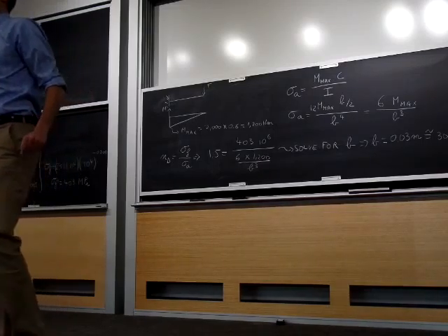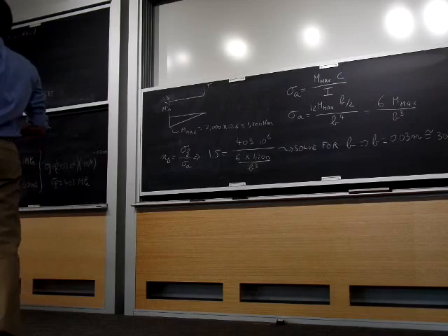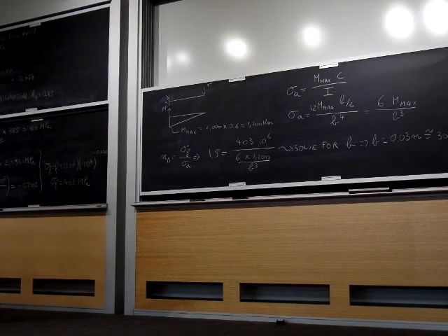So now that we have those values, how are we going to go back and check KB? That's the next step. I just wanted to make sure before we did that everybody is on the same page. We started from our design factor. We said it's the fatigue strength divided by the maximum stress occurring in the design. We calculated sigma f based on our endurance limit.